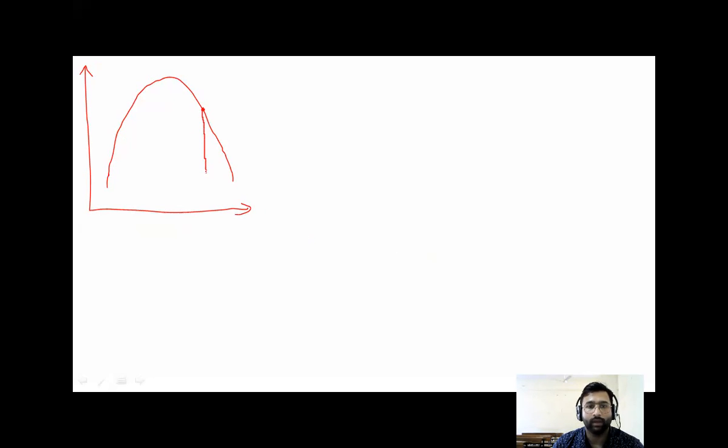So here it will be isentropic, and here it will be like this. By default, always assume point 1 is liquid saturated. So some assumptions you have to make. Point 1 is always liquid saturated. Again, it is pump, and then you will get point number 2. Point number 3 is given dry saturated, and point number 4 lies in the wet region.